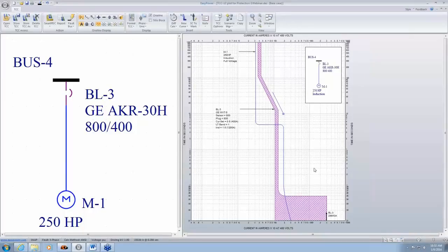So what we need to do is, when we start the motor, the circuit breaker trip curve needs to be on the right side of the motor starting curve. Now, at the same time, another thing we need to be careful about is this is supposed to protect the motor circuit, this thermal protection. So the long time delay here can be adjusted so that the tripping time is faster than the stall time or the I squared T damage line.